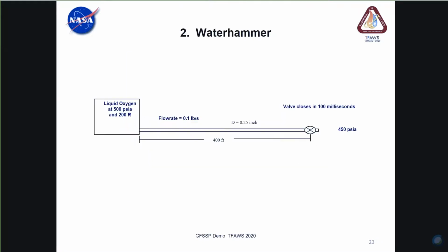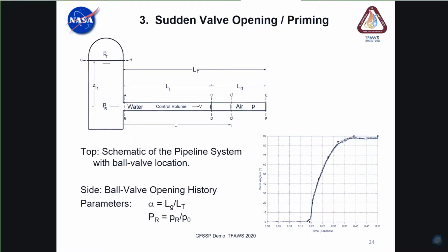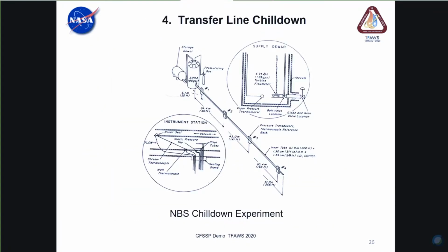So yeah, in water hammer type analysis, you're trying to capture the change in density with respect to pressure. And if we had only done one pipe, it would have been all the same density throughout the pipe. So to capture that change in the pipe, we discretized it into 5 segments. In fact, that particular model was also run with like 10 pipes as well to see the effect of discretization. But going from 5 to 10, there wasn't a big effect. But say going from 5 down to 2, that does affect your answer.